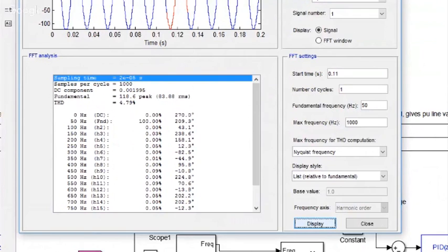If your model is not correct, the multi-level inverter model you have made, it is not correct, even harmonics will come here. Okay, I have models like that also, so you have to be very careful in making the inverter. Whenever you make it, you have to see that even harmonics are cancelled. So you can see here, even harmonics, say fourth harmonics, sixth harmonics, eighth harmonics, all these are 0.